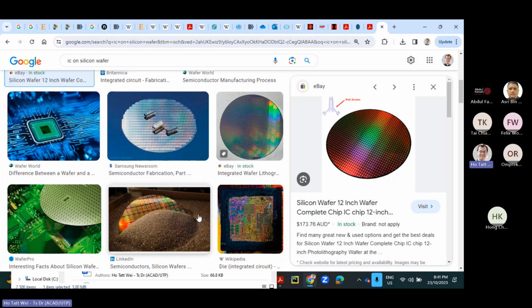When you make the transistor nowadays, photolithography is a process where you are using light to create patterns on the photoresist so that you can cut away these patterns, and you're playing some fancy optical tricks. In the old days, when you were at 180 or 200 nanometers, it was still appreciable, because the wavelength of light used to create these patterns is on the order of 157 nanometers. So it's in the deep ultraviolet wavelength.